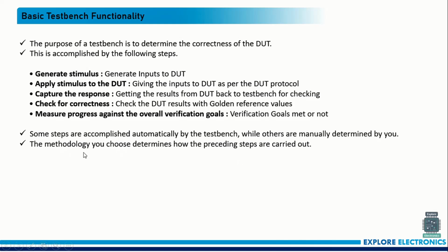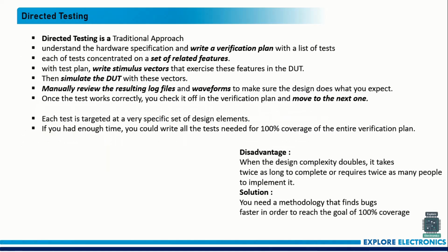So that's why the methodology we adopted will determine what steps we need to carry out manually and what steps are carried out by the test bench on its own in the tool. Then we need to understand directed testing. Directed testing is an old, traditional approach. We can easily compare this with the Verilog test bench we are going to write.